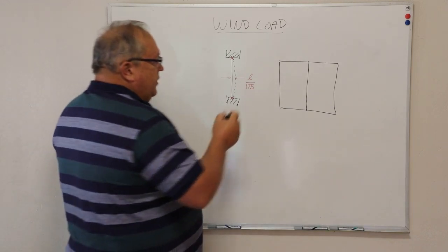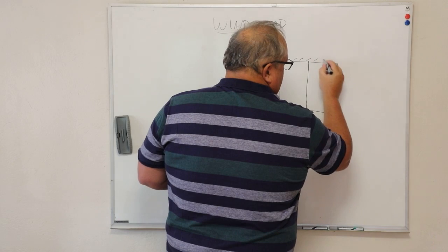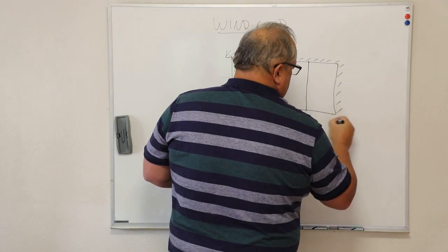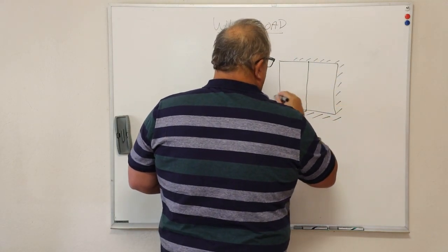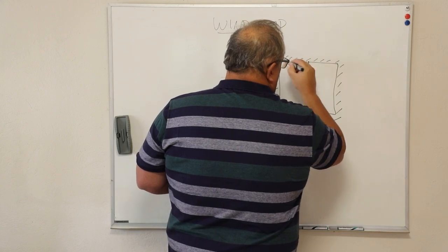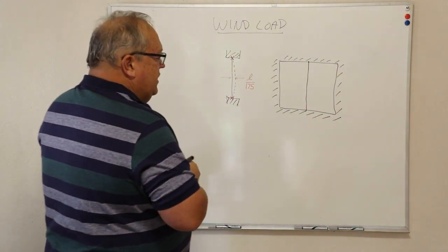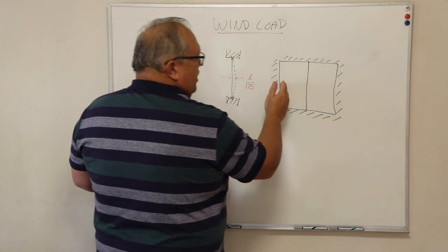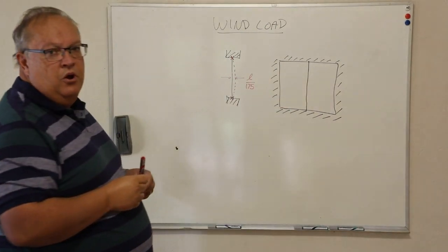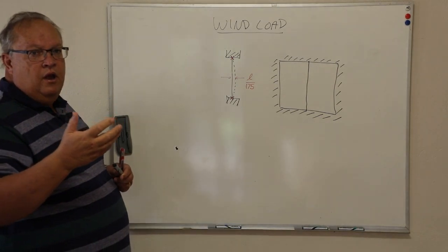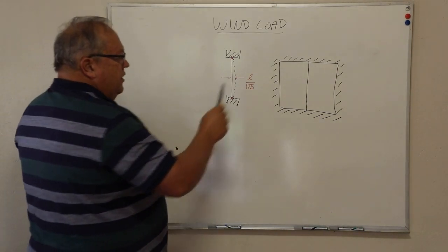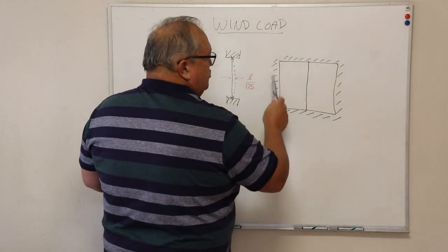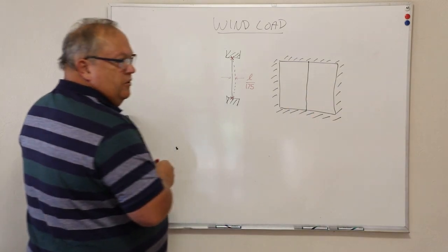In other words, I'm going to assume that all the way around this frame it is attached to either the brickwork or a concrete beam or a lintel or whatever the case is. And as long as I fix my frame sufficiently onto the brickwork or the concrete lintel, I'm allowed to assume that that brickwork is strong enough to support the wind load on that frame.